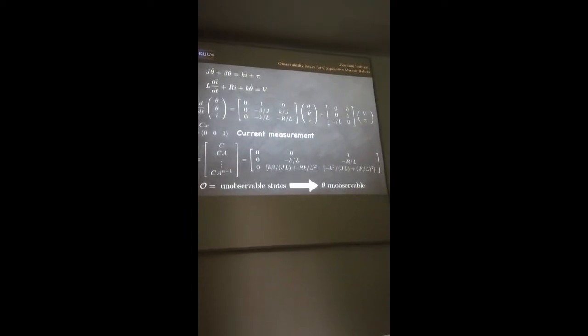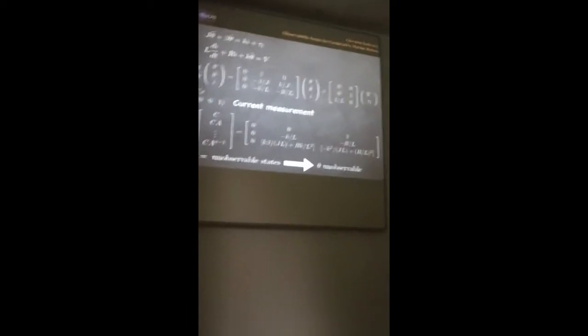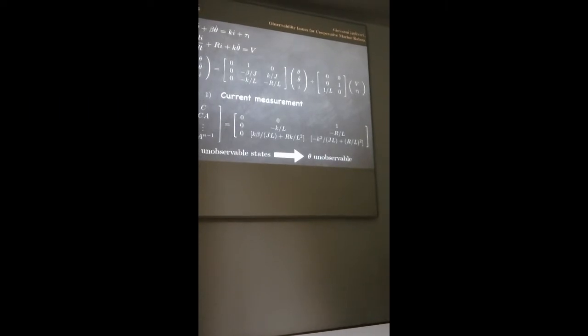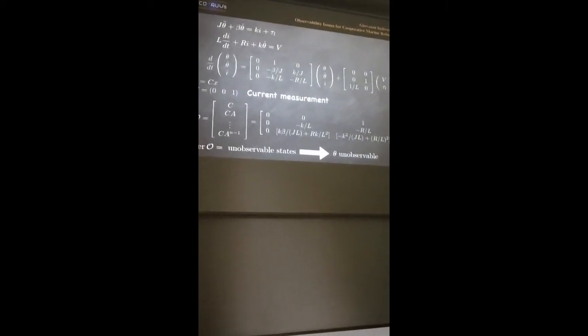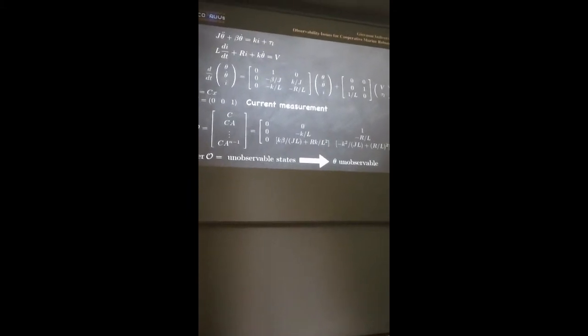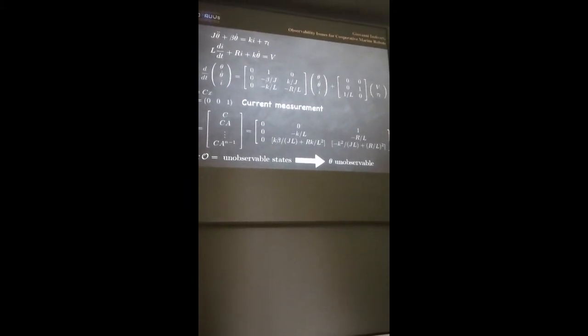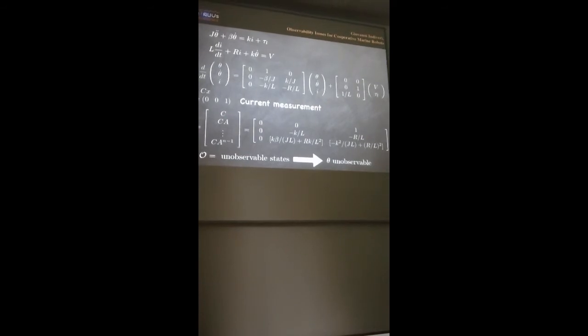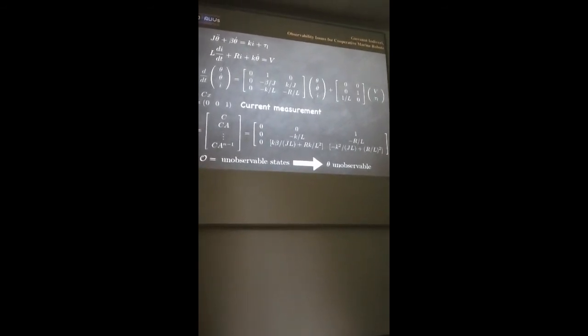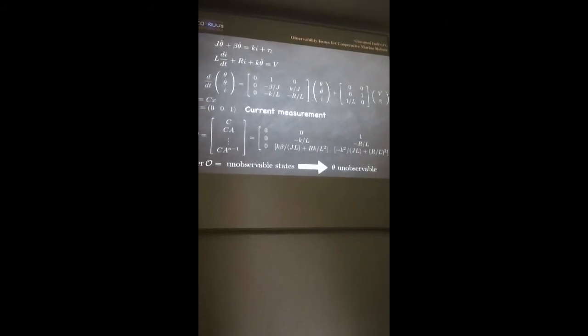If you have those measurements, then you can do a lot in terms of low-level control. Because as Andreas was mentioning, if you measure the current absorbed by the motor, you have a direct measurement also of the load. So if you get entangled in seaweeds or whatever, you will tell immediately. So it's also very easy to do fault detection. If something goes wrong, your current will go up and you can tell.